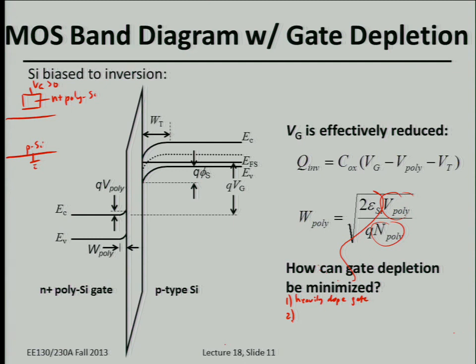What we can do is take extreme measures to melt the gate. There's pulsed laser annealing, where you use a nanosecond-long laser pulse to temporarily melt the silicon, and it turns out that way you can get a lot of the dopants residing eventually on substitutional lattice sites, so you can effectively increase the dopant concentration in the gate. So that's one way. What's another way?